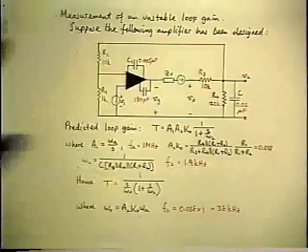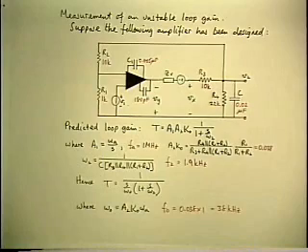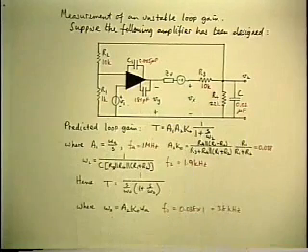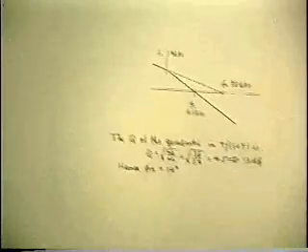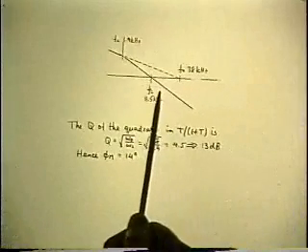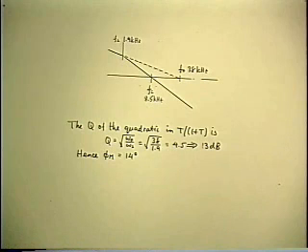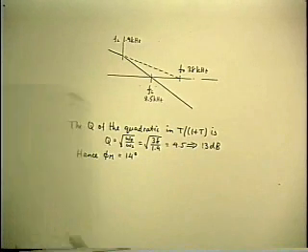Well, let's follow through with the example, because the purpose of doing this is to know what was wrong with the model that you started with. So the prediction was that the loop gain ought to look like this, which ought to have had a positive phase margin, and so it should have been stable, but it really wasn't.